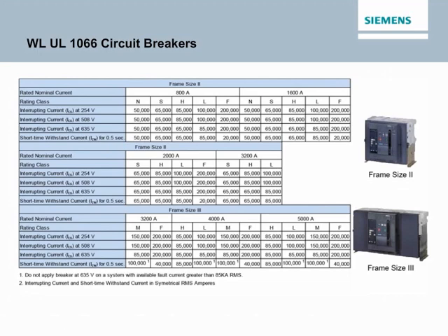One important low voltage power circuit breaker rating is its short time withstand current rating. This rating indicates the level of current that a breaker can handle without damage for a designated short time. This rating is important because an LV power circuit breaker is often required to delay tripping for a short time when a fault current is sensed so that a downstream breaker closer to the fault has time to trip, thereby avoiding a larger system outage.